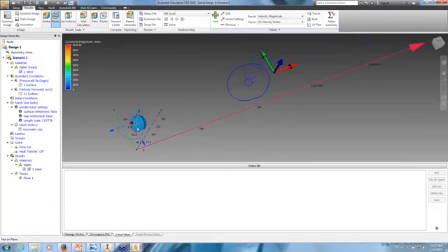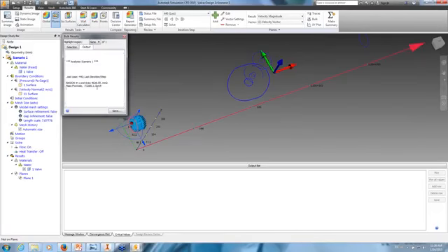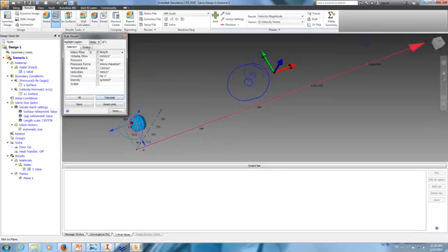So now I aligned it to the inlet, where I can use the bulk calculator to, let's say, calculate the mass flow in whatever units I want, let's say pounds per hour. And if I click calculate, it's going to give me that value, how many pound mass per hour. I can request any of those output results. In the next example, since we have temperature as well, it'll be more interesting to see what kind of results this bulk calculator gives me.